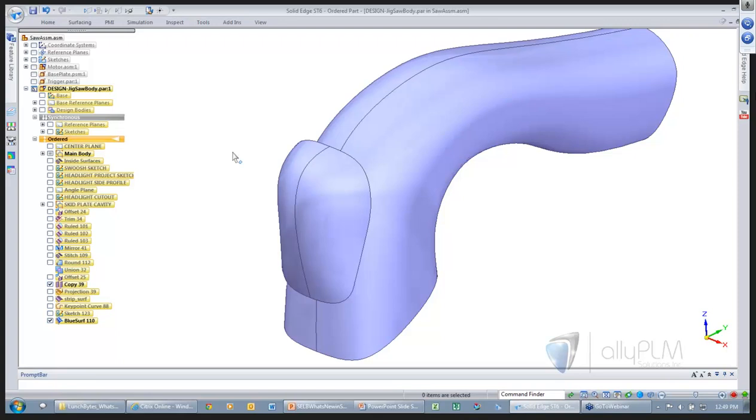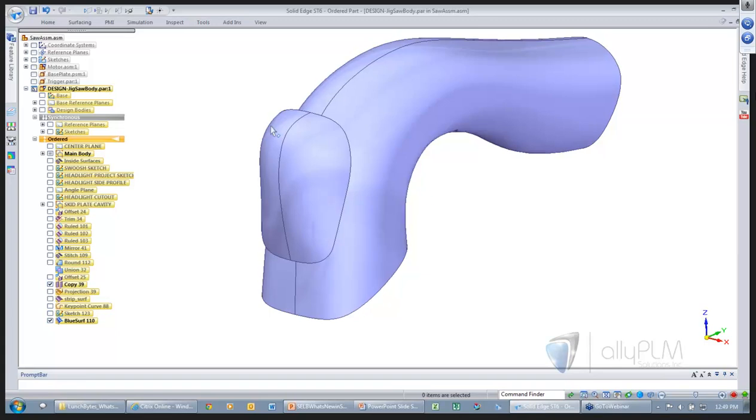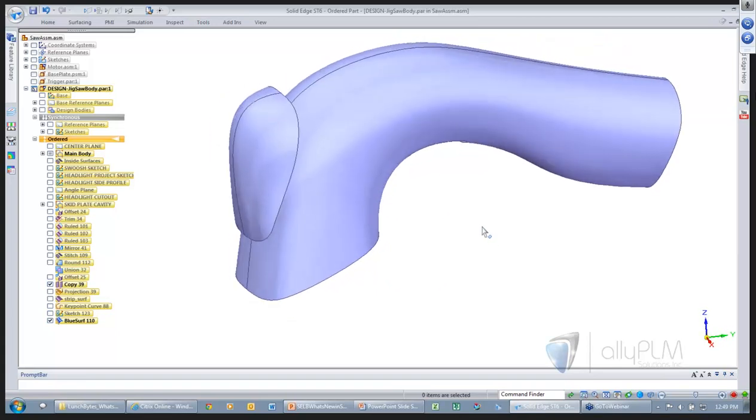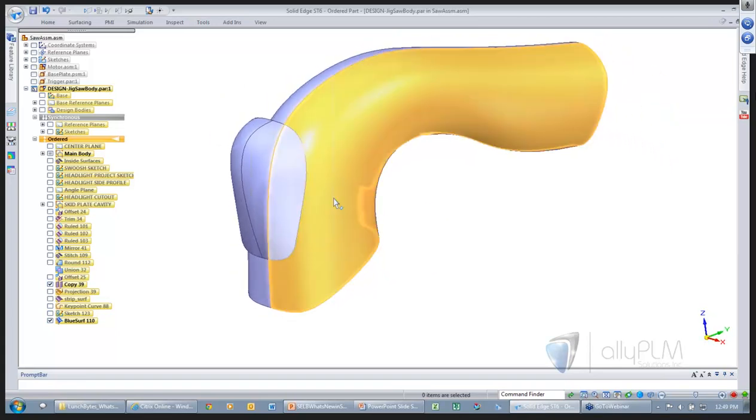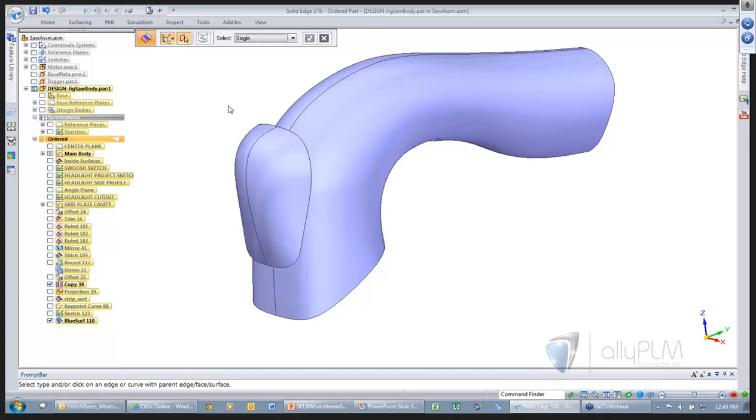If I turn back on that reflective tool that we saw earlier, now you'll see what I get when I mirror it. Now before we do anything with that, I need to create a ruled surface which will extend back so it intersects with this copy face, so that allows us to trim, is what I'm trying to say. So we have another option. Maybe I do a tapered to plane, and I'm just going to taper it back to this plane. Grab the edge which I want to sweep.